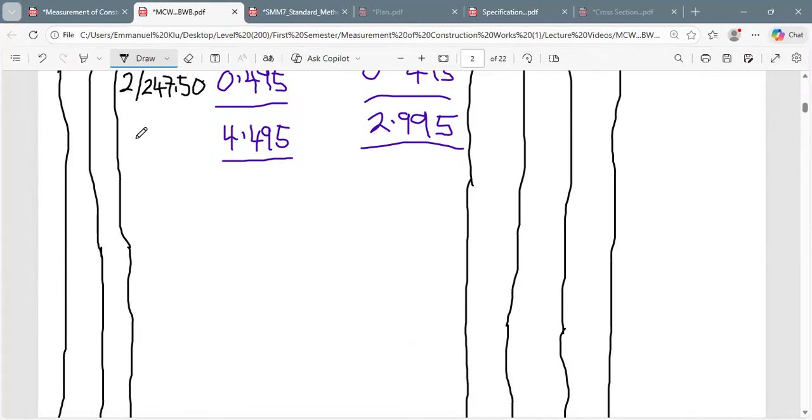So we write over here: excavation of topsoil for preservation. Average depth of what? 150. The topsoil there, always excavation of topsoil is what? 150. You should know that. Any site, anytime I'm going to do excavation of topsoil, anytime you get a fresh site you want to build, you have to do excavation of topsoil, and that dimension is always 150. Thank you.